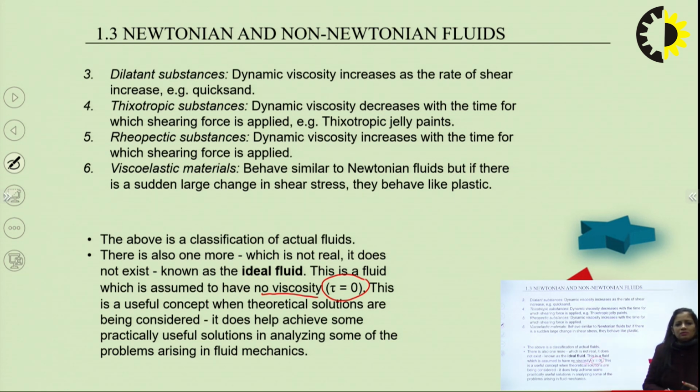This is not a real case, but analysis based on ideal fluid assumptions is still very helpful in achieving practically useful solutions in analyzing some of the problems arising in fluid mechanics. So we use this concept in solving some complex problems. Although ideal fluid is not a real fluid, in this we assume that there is no viscosity between the fluid layers and also no shear stress.